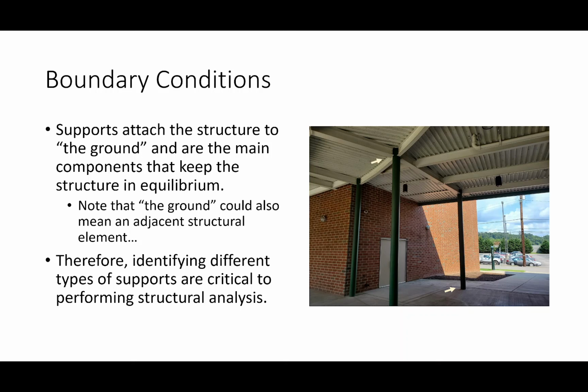Now, this boundary condition here might behave much more like a pin. So imagine that instead of a fist, maybe I'm just holding it with my finger. In other words, it won't translate, but maybe it'll rotate. My finger can maybe hold it in place, but it can't prevent it from rotating. Does that make sense? If I were to keep my finger here and move the bottom, it's not translating, but it's certainly rotating. So maybe a pin boundary condition would have unknown forces, but it wouldn't have unknown moments.